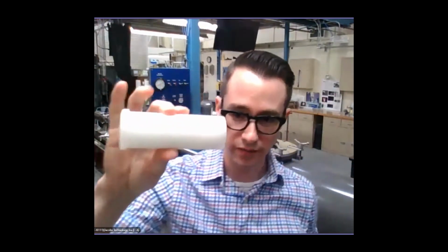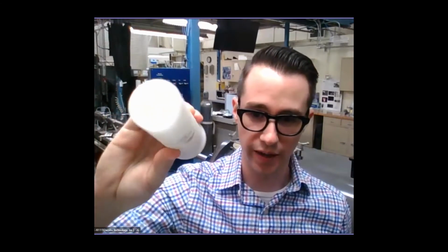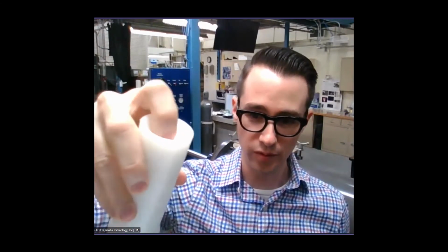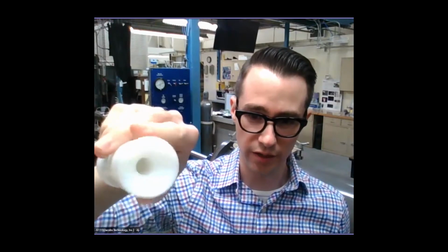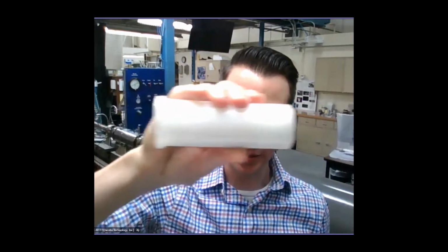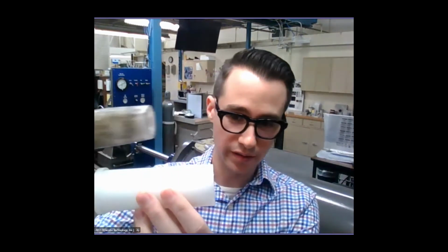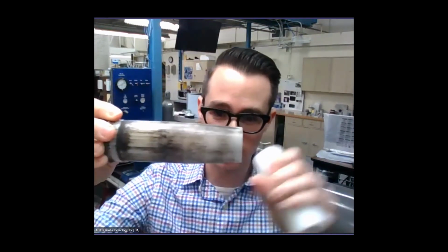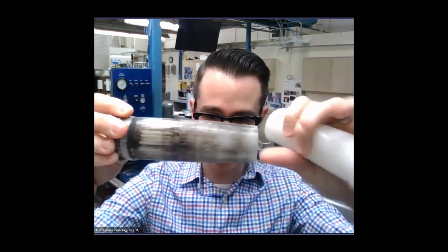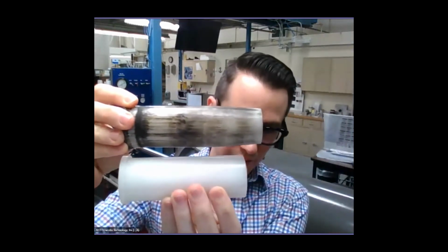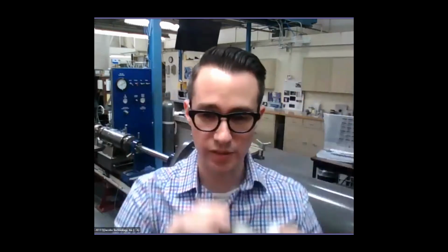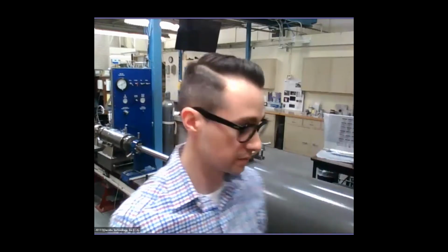So here's one of our Teflon pistons. We machine these in-house. It's a consumable. It has a conical shape at the end. And that is because if you remember from that drawing, which I didn't point out, so that's my fault, but the very end of the pump tube is tapered. And so here's a spent one. This one has been accelerated down to accelerate the hydrogen. And you can see how it has this tapered shape. Well, it didn't start out tapered. And so this eventually stops itself and doesn't embed itself in the barrel.